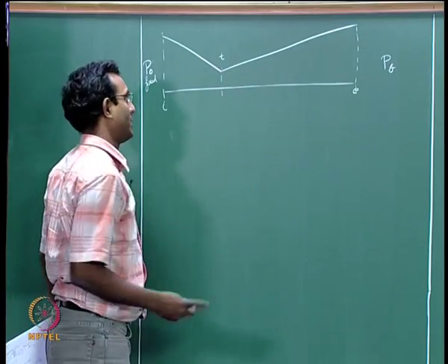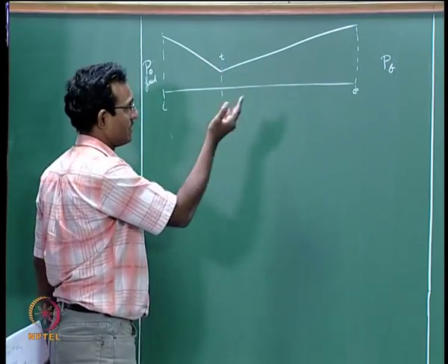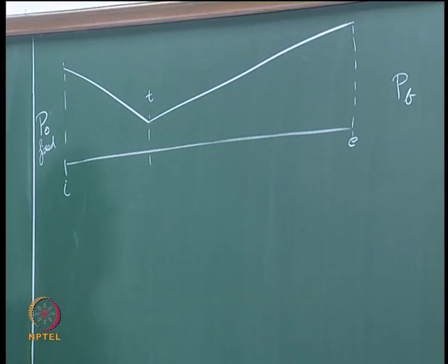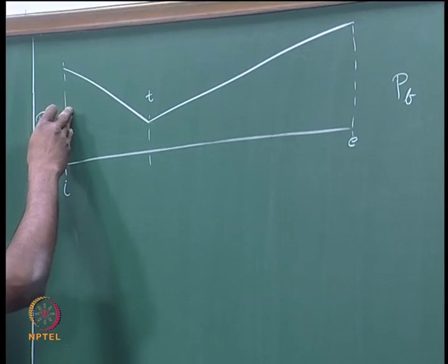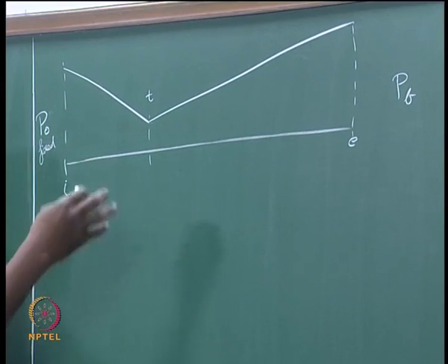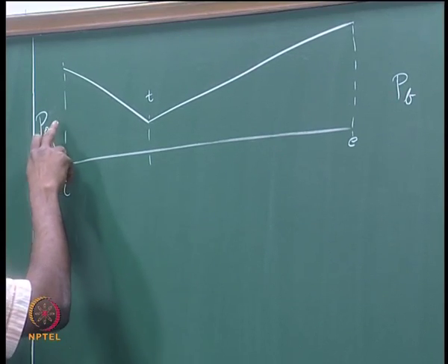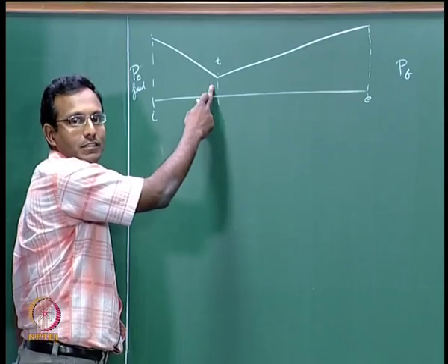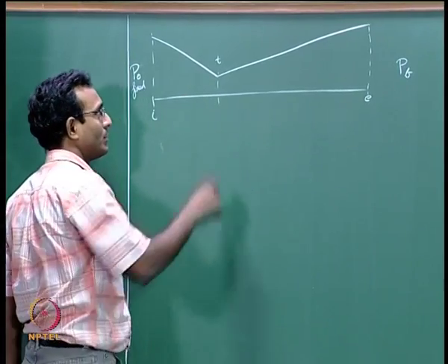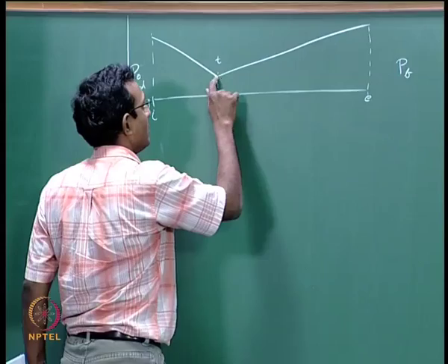When I slightly decrease the pressure there, immediately the pressure differential will drive the flow, and when the flow starts, we know it is going to be subsonic because it was stagnant just before this. In the subsonic flow convergent duct, the area decreases, velocity increases, and Mach number increases, and after that it will still be subsonic.